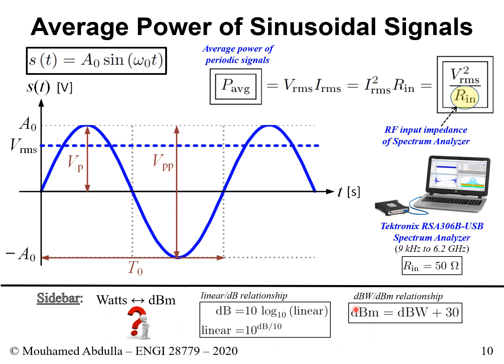So to me, these three equations are enough for me to deal with dBs and watts, and I think it's the same thing for you. I solved many of these questions related to dB and dBW, and in fact we have a bunch of questions related to this in assignment 1. So please go through them. I would assume this is something that you've seen before, but if not, please go through them and see that you're doing this appropriately. This is an important skill that we will use in this course and in other courses as well.